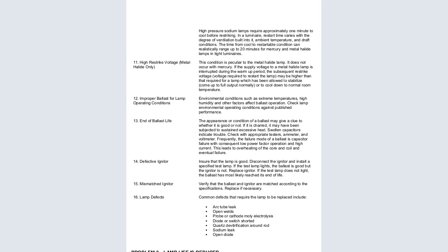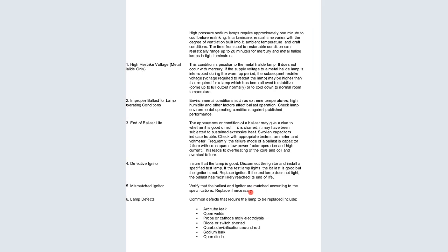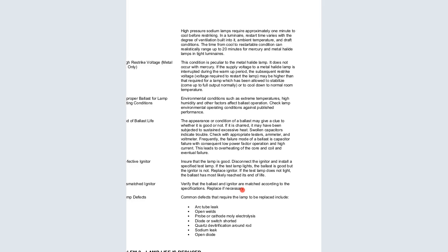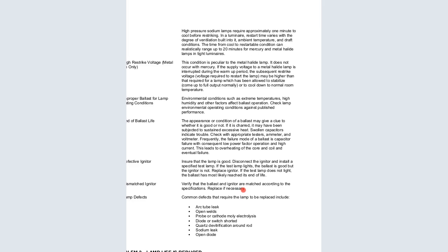So what do we do? Environmental conditions such as extreme temperatures, high humidity, and other factors affect ballast operation. So check lamp environment operating conditions against published performance. And then end of ballast life.